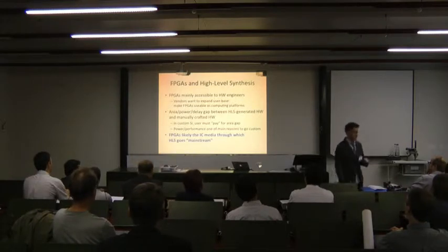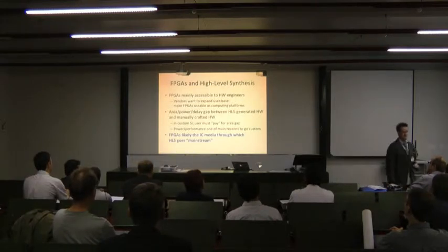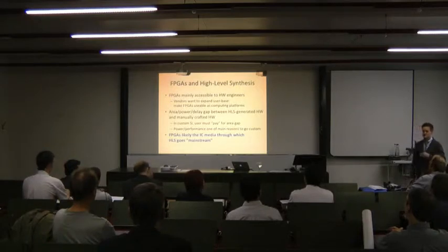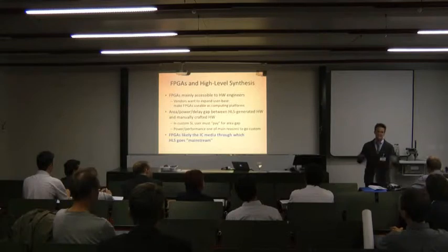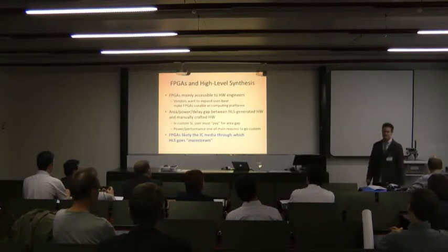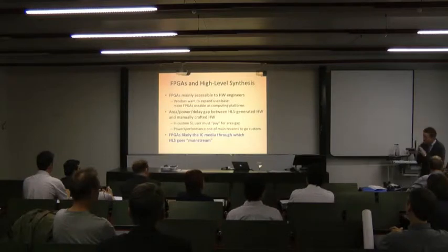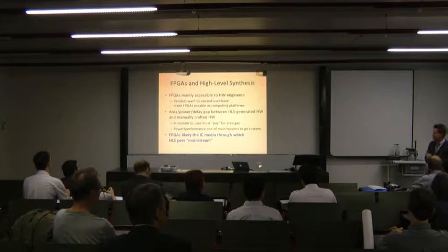I'm not as optimistic on that. I think high-level synthesis can do very well in certain applications, say streaming applications, heavily pipelined applications. I'm doubtful on whether, for example, if you think of an FFT and think of how that's implemented in hardware, a spatial repeated butterfly layout, it's very tough for high-level synthesis to ever be able to synthesize something like that. However, for certain applications, I think high-level synthesis could do well. But I think there is a gap between high-level synthesis hardware and human-crafted hardware.